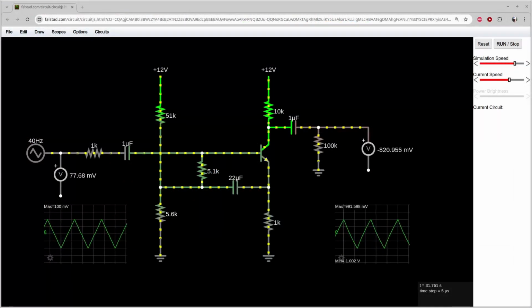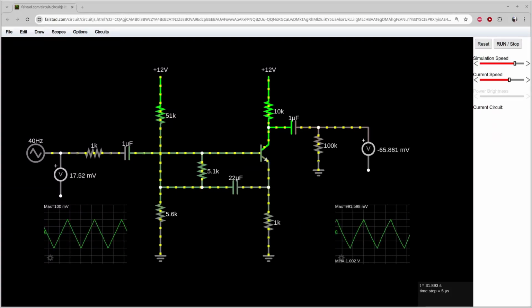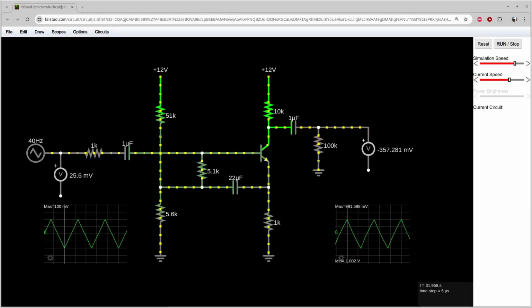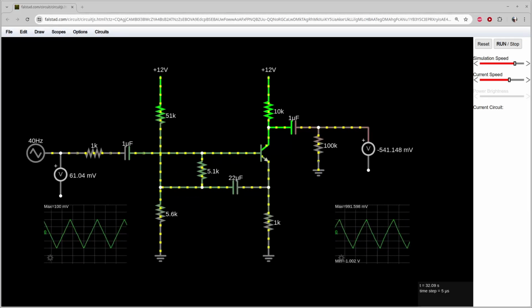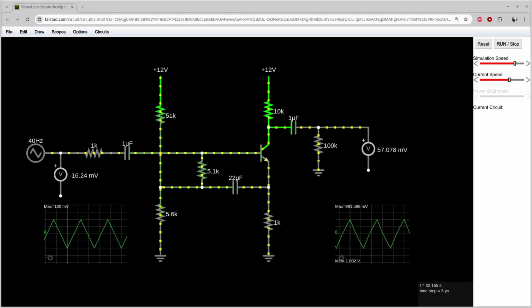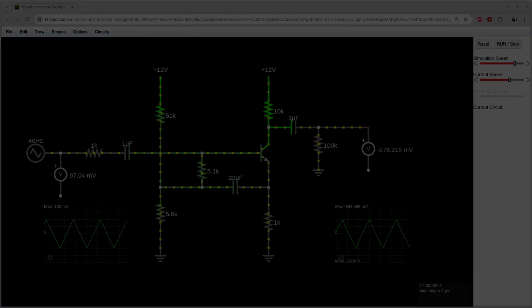What we designed looks pretty good on CircuitJS. 1/10 of a volt goes in, a volt comes out. But I never trust the math or the simulation. I'll inflict some elevator music on you for a time-lapse of me fumbling trying to get component leads into the breadboard.